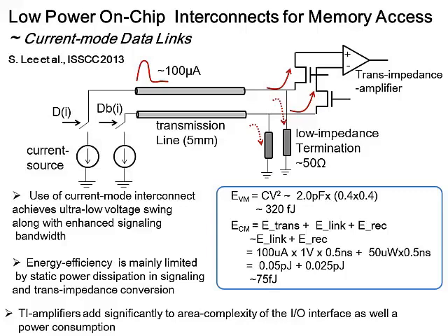So although we are incurring a good amount of hardware complexity by introducing these analog mode transceivers on on-chip data links, we do not get a huge amount of benefit. It remains around 2 to 3x as compared to conventional voltage mode links. So we'll see how spin torque based sensors can help us achieve very low power for these current mode data buses as well as current mode sensing schemes.